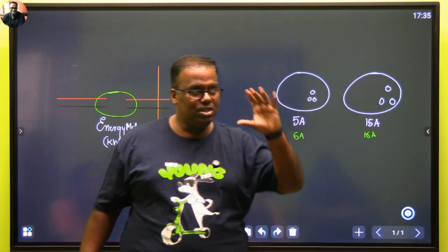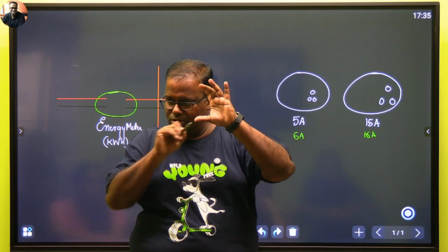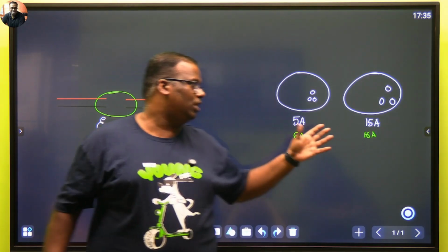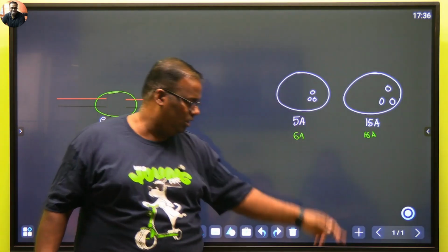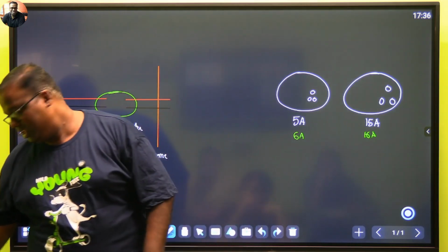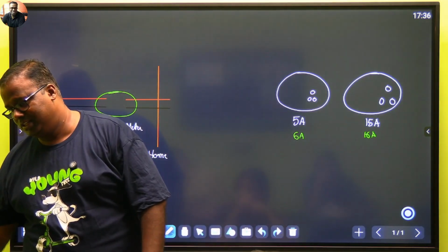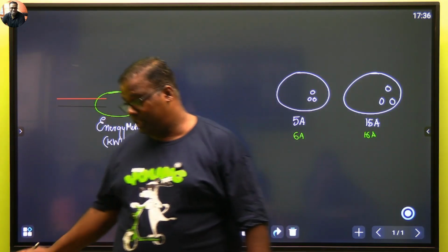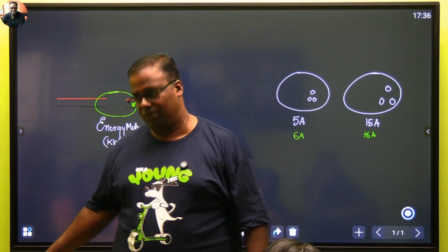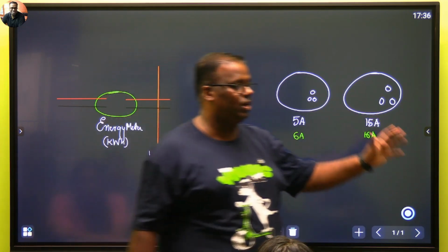But sometimes have you seen some sockets where you have got the bigger ones also and the smaller ones also? So we call them combo. It's best to buy the combo, 16 as well as 6. Look at this one. This is a 16 and 6 combination. You can use it for a 16 and a 6. You can use it for a 16 only when the wiring has been done for 16. Okay, it's not about the socket, it's about how the wiring goes.